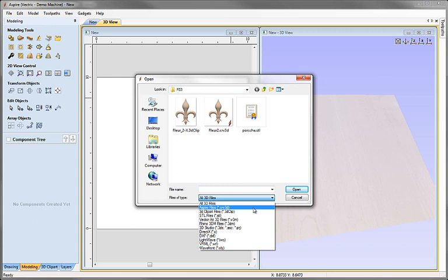Aspire files are .crv3d, .3dclip, and then also you can see the V3M files listed from the Vectric 3D website. We also have the other file formats listed: STL, Rhino files, 3D Studio, and various others, and they're all essentially 3D mesh files, and we'll look at importing those in a moment. First here, I just want to look at the difference between a 3D clip file and a CRV3D file.